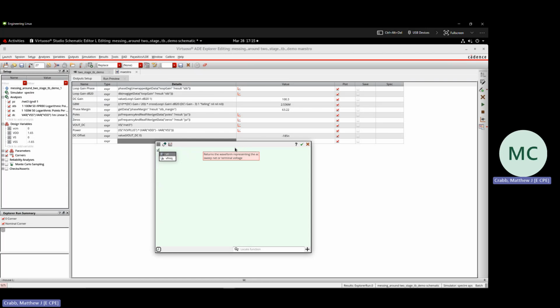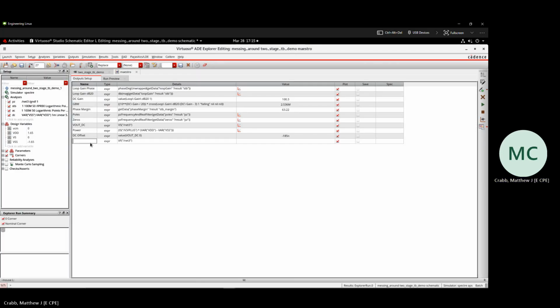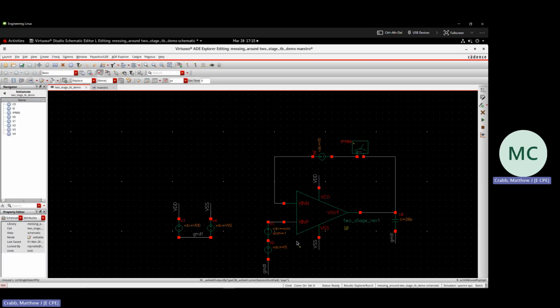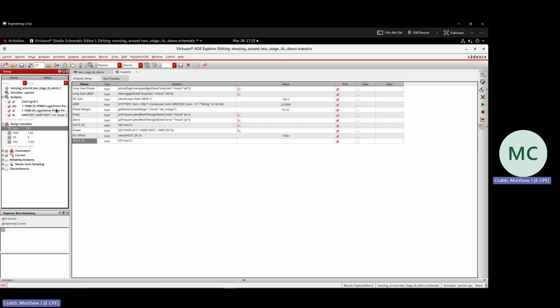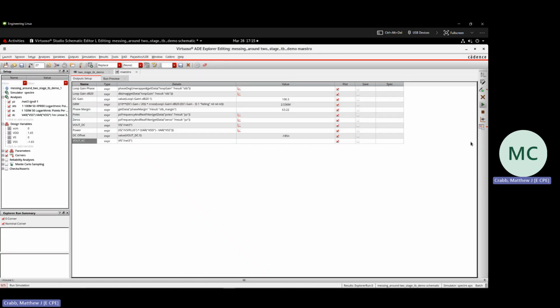This will be VF for a frequency sweep. And then I'll select on design and select this Vout node. Check. And then we'll call this Vout AC. And so now all we're doing is just a typical AC simulation where VS will be set to 0, VCM is set to 0. So we're at our common mode input point of 0 volts. And then we're just putting this in a unity gain buffer configuration and running an AC sweep. So I'll go ahead and run this.